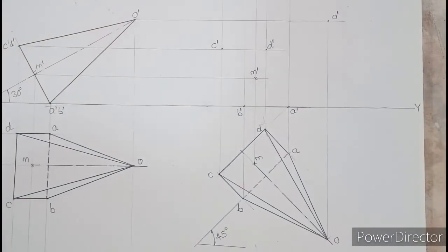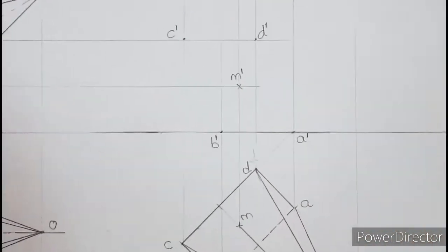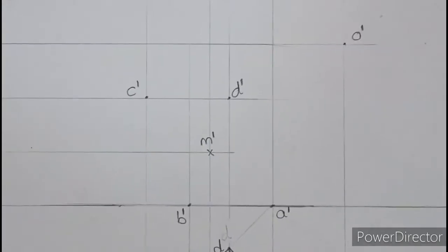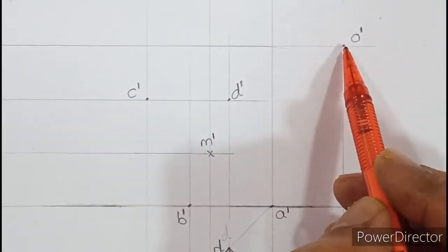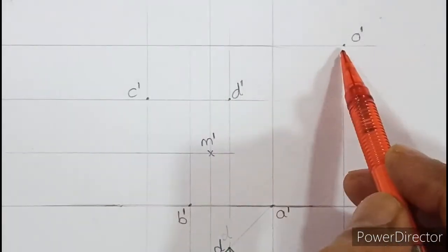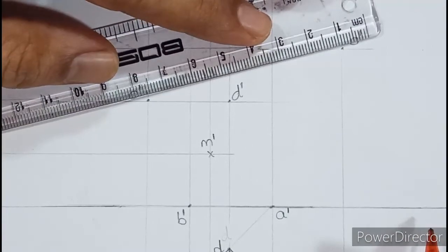So now how to connect these points? So step number 1 remains same. Join the outermost points with a dark line. Okay, so let me enlarge a little. So here the common mistake made is that students join O with D. So outermost point doesn't mean you have to join in sequence O to D, C, B, A, D and O. Not like that. You have to align your scale and join the shadow of the object.